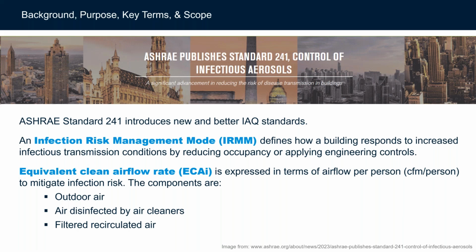We designed for fire in case of a fire, so think about a stairwell. Oftentimes the stairwell is typically negatively pressurized, but if you have a fire, you would actually turn on an extra fire-rated fan to pressurize that space so that you can evacuate the smoke out of that stairwell chamber and then allow people to exit. That would be the fire mode, and you have a fire marshal that might come out once a year and test that to make sure that it is in fact still operating correctly.